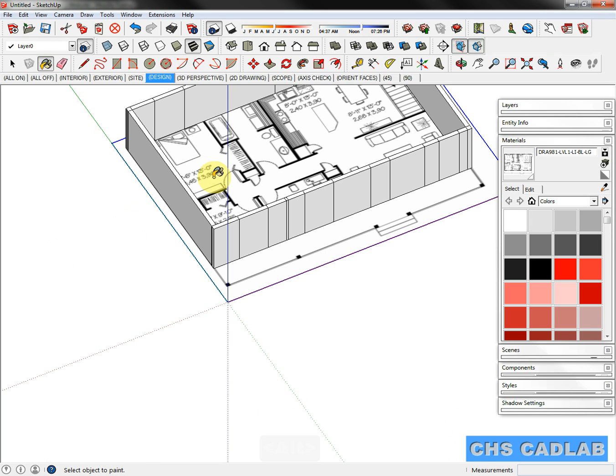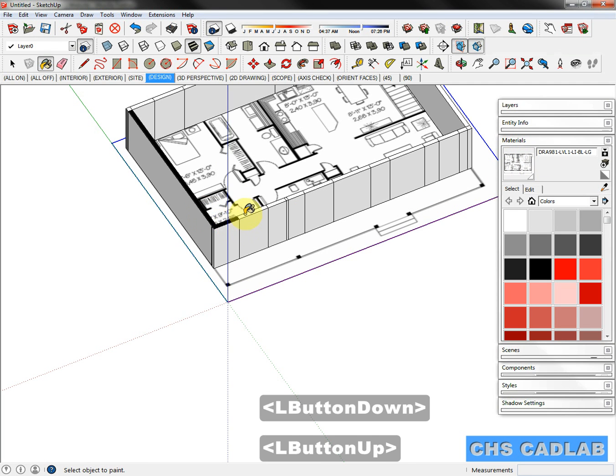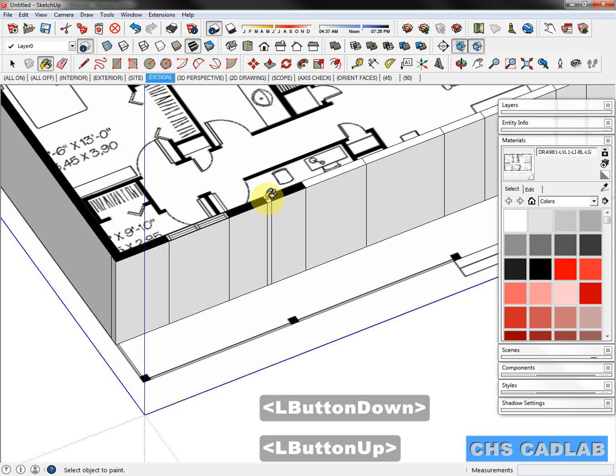All right, so I chose the paint bucket tool now, once I've got all my walls pulled around there, the outside walls anyway. And then I chose the paint bucket. I hit the Alt key. Notice I get the eyedropper. And then I click on the image. And you notice the material I get is the image of the floor plan. And then I can paint on top of the walls. Whoa. And so you'll be able to see exactly where the windows are, where the doors are.